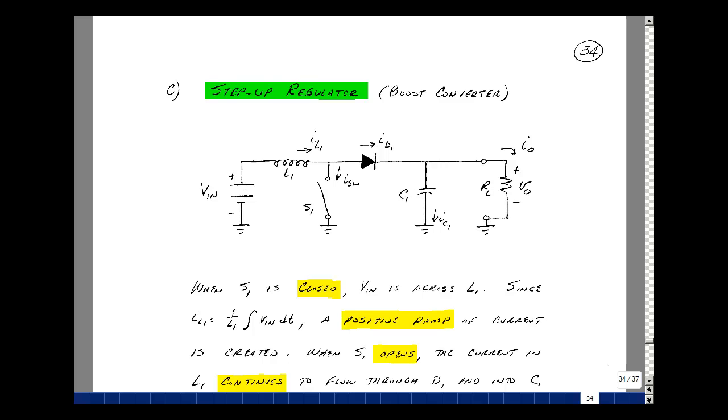It was a sine wave that had an exponential envelope around it, and the frequency of oscillation was around 320 kilohertz for this case. If we take the value of L and the values of the stray capacitance in the circuit, 1 over 2 pi square root of LC, you roughly get about 320 kilohertz. This frequency does cause a lot of noise and interference problems,